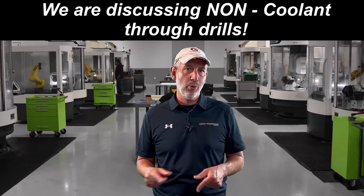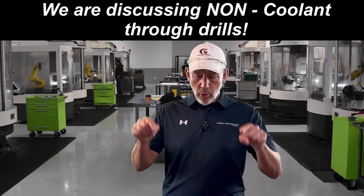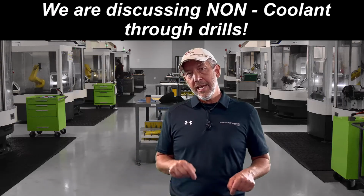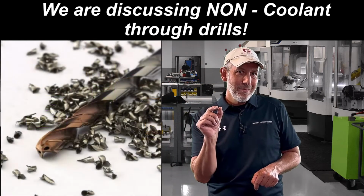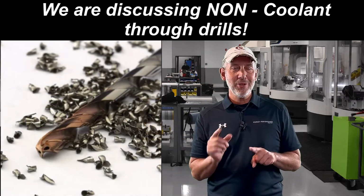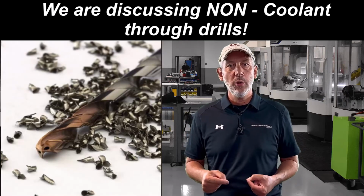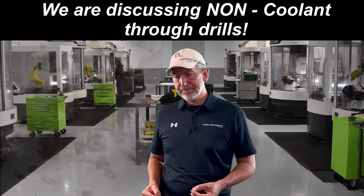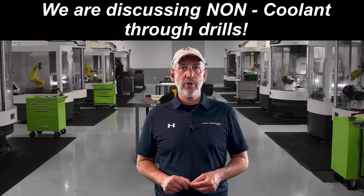Again, this is very important why we go with material specific, because what we want to do when you're doing a deep hole or you're drilling anything more than 4 times D is you want to make sure you break the chip into small segments, because if you don't break the chip, then you can't do number 2, which is to hold the chip, which means the flute can't hold the chip. So we need to break the chip. So how do we break the chip? Well, number 1, it's on point geometry. That's what we're going to try and do to break the chip.